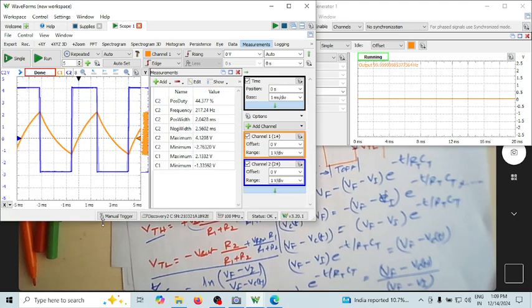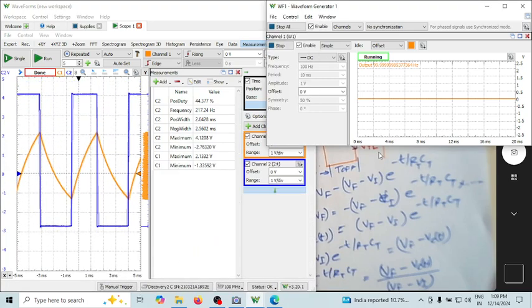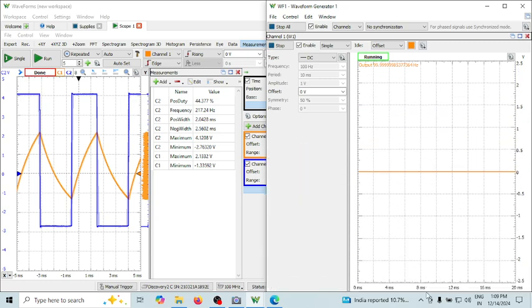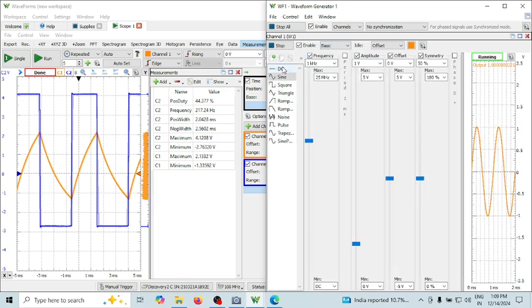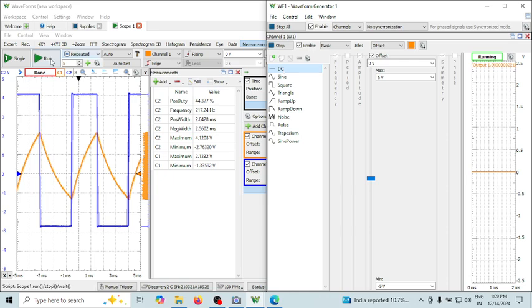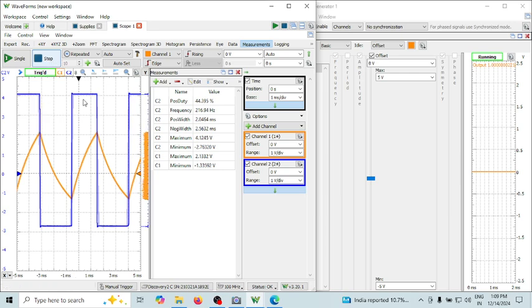Now you can lively see how the duty cycle changes when I change the reference voltage. Let me make it DC, and let me just keep running this all the time. Just have a look at the duty cycle. The duty cycle is 44% because this is now 0.